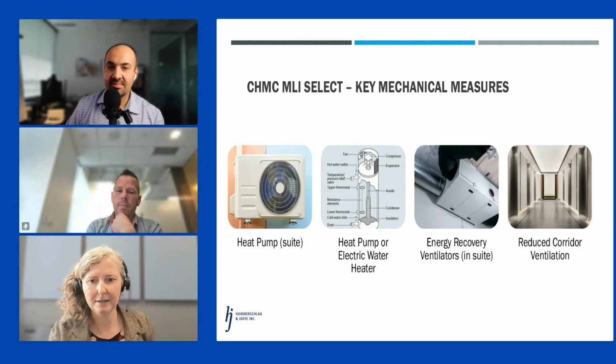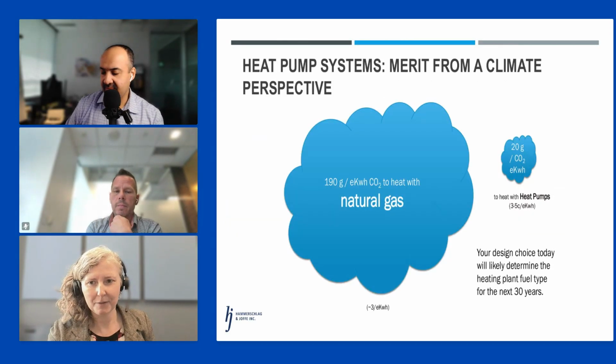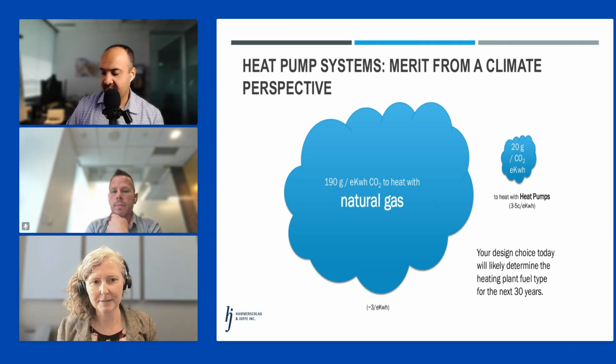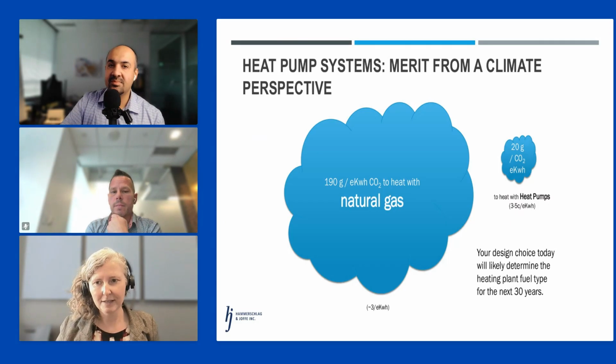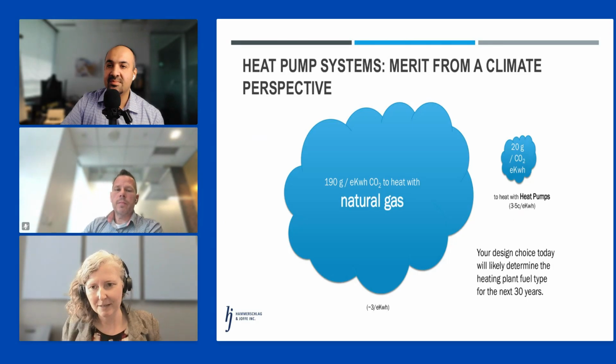40% reduction. So when we say heat pumps for suite heating, first, why? More important than the energy savings, the coefficient of performance of a heat pump, which measures how much heating is produced by the machine compared to how much electricity it consumed to do it, is usually somewhere between 2.4 to 3.5 to 1. And I'm estimating here based on seasonal averages. So over the whole year, if you took the amount of kilowatt hours in and the amount of kilowatt hours out.